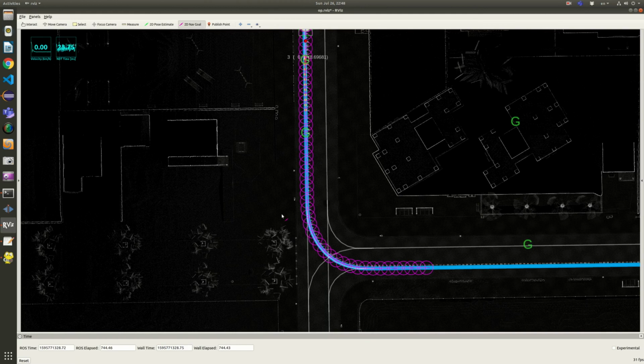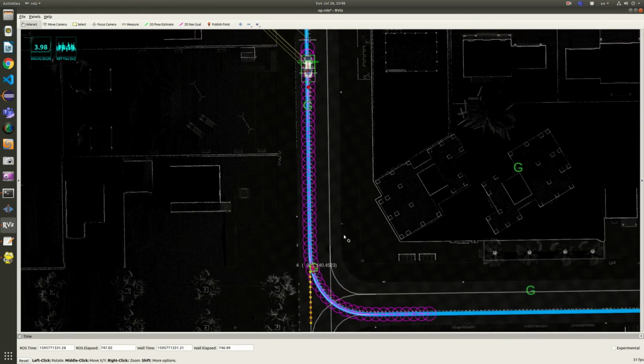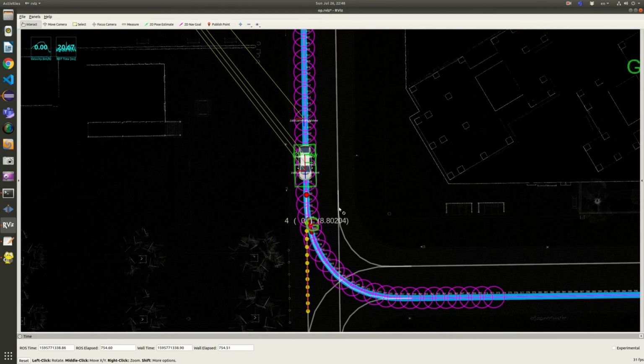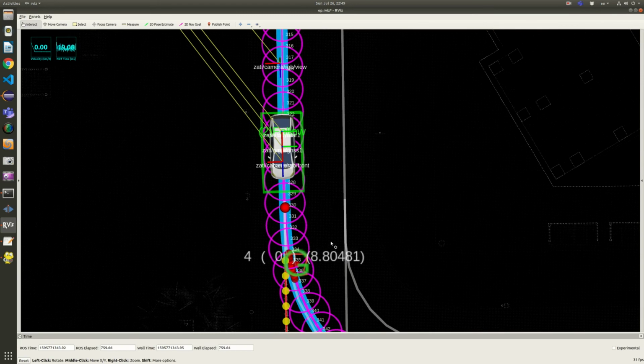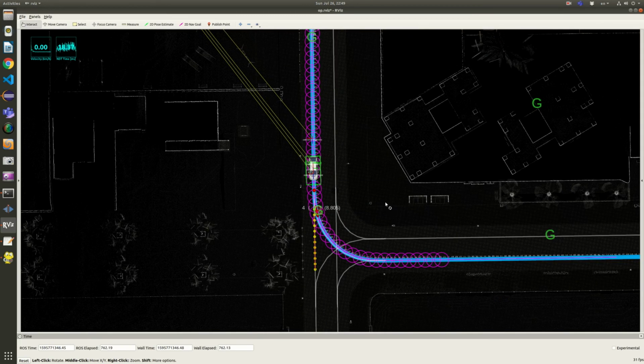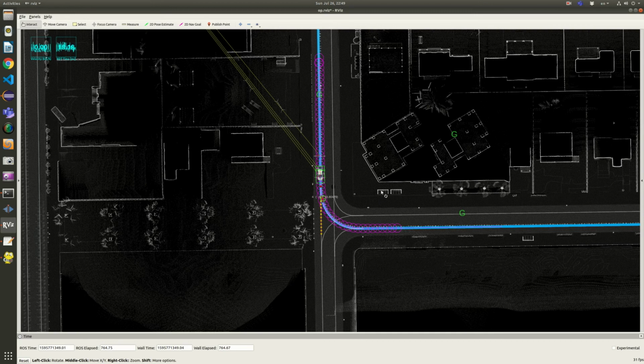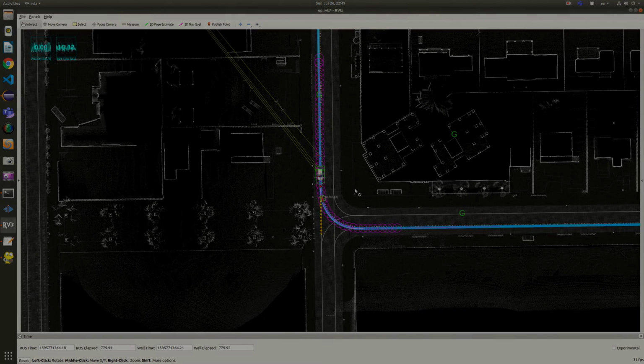Another test: let's move it a bit further so the car accelerates and brakes before the obstacle, around 8 meters from it. So successfully, for this configuration we set the distance for braking in normal circumstances. This will happen over and over, so it's a predictable result.